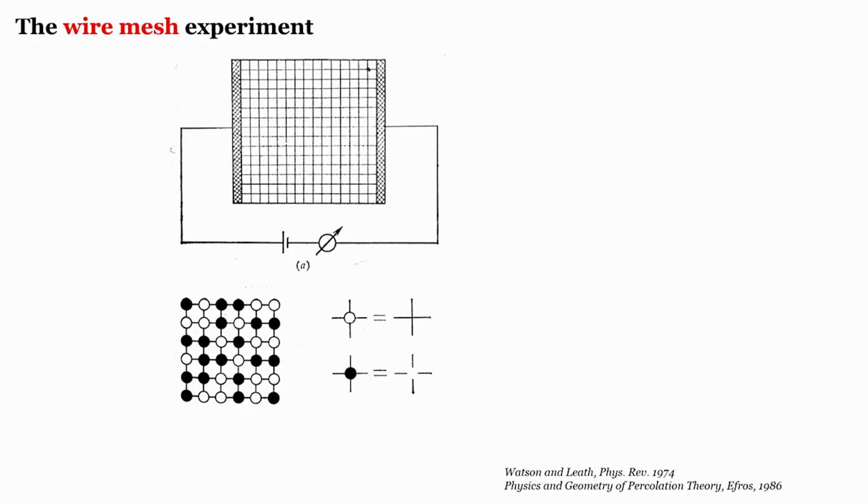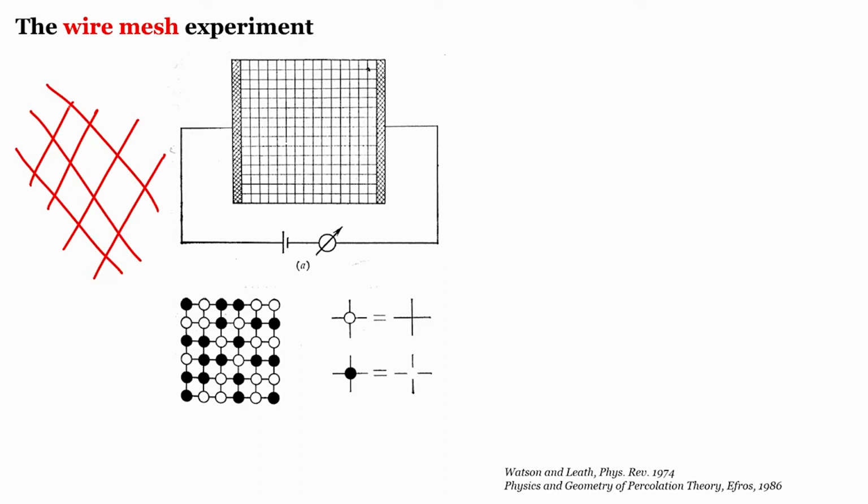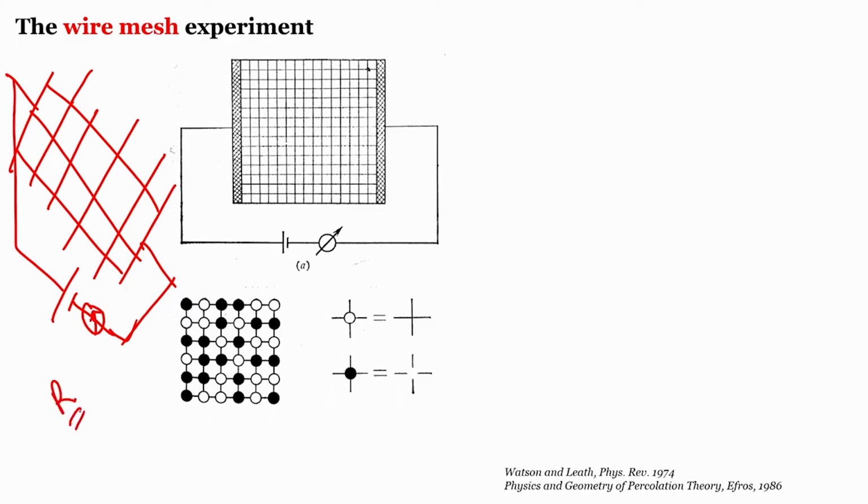What you do is you take different strands of wires and then you solder them or connect them by some other means, and then you have a common end at each side, and then you apply potential. Now you measure the voltage drop and hence eventually the resistance. So you can measure the resistance of this wire mesh.